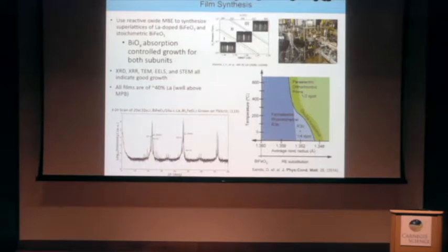We used various characterization techniques: diffraction, reflectometry, X-rays, and various TEM. I'm going to show a bunch of TEM data. EELS and STEM all indicate good growth and high-quality films. And as I said, this chemistry is important. All of our lanthanum-doped layers are well within the paraelectric state.